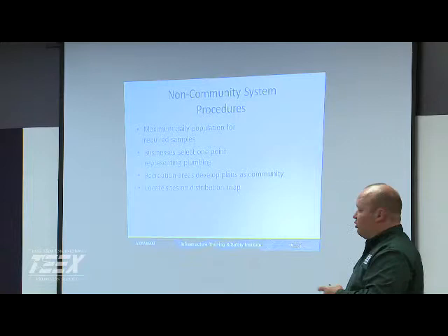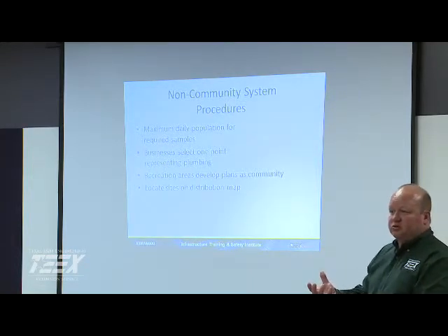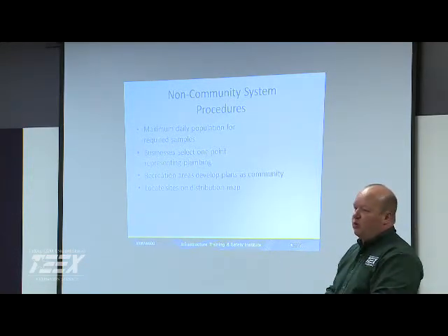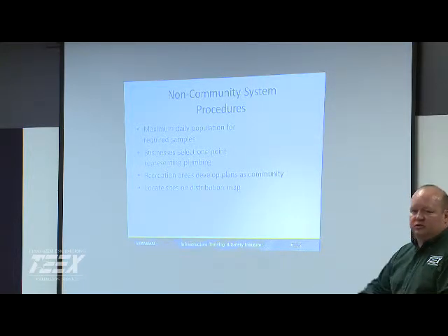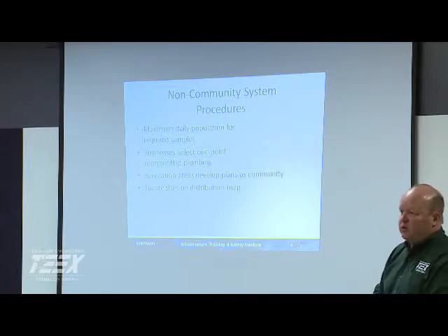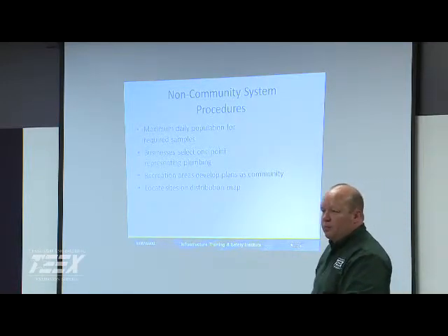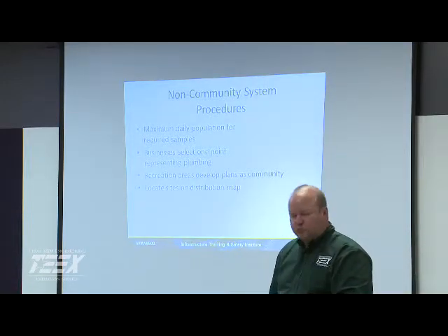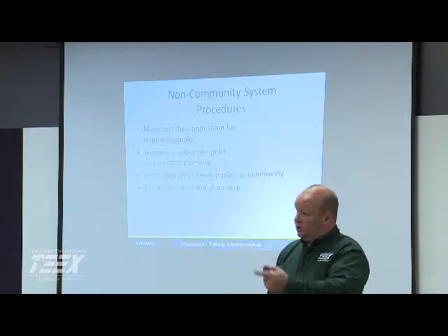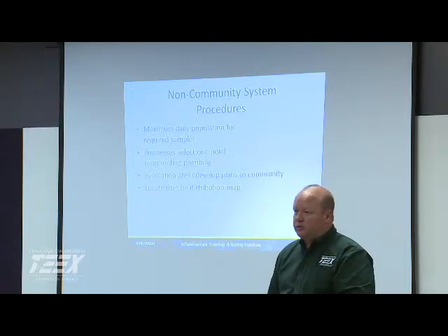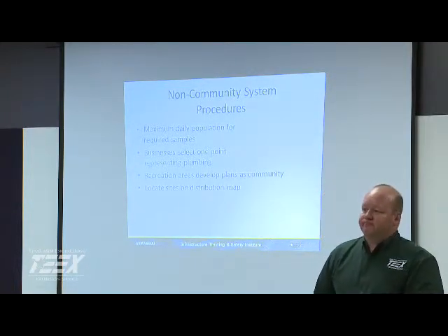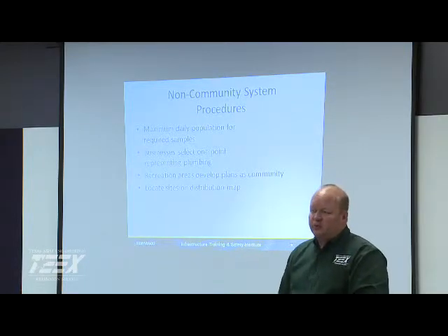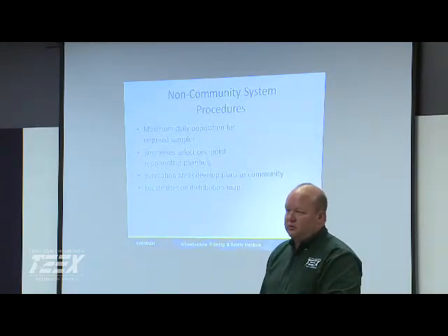Distribution maps, I don't know if y'all are getting into GPS locations, and that's an awesome way to go in, easy handheld devices, tell where your valves and stuff are. We've got all of our meter boxes now with the GPS, because we went to the AMRs, and now we're losing our meters because the grass is growing up over them, so we don't open them to read them. So now we have GPS on all of them, so if the customer has a problem, we can just take the GPS out there and find it.